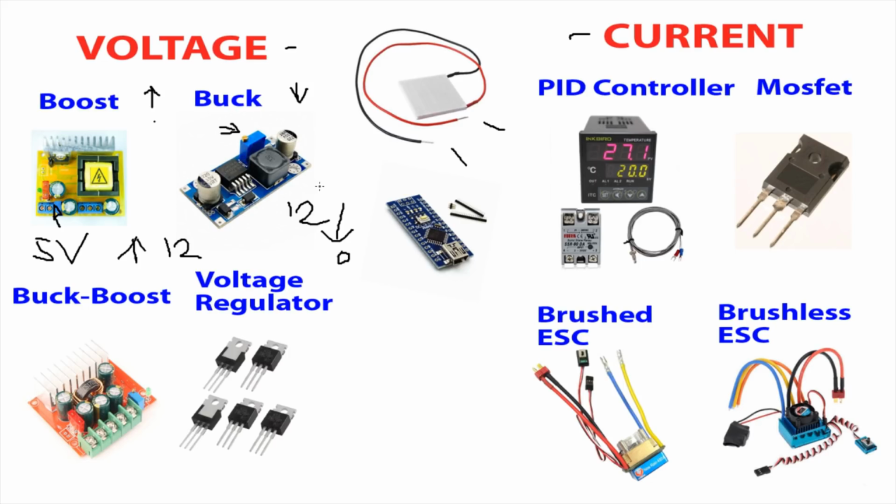But these are pretty jolly useful. You'll be probably powering it from a car or from a PC power supply. You want to control your 12 volt-ish TEC. You can then just turn the trim pot to adjust your output voltage, which will relate to a temperature. So these are highly practical, but be aware that you may not be able to actually stop all of the power going to the TEC unless it can go to 0. However, you may say if it goes to 0.8, the amount of power it's going to be drawing is so small that it's not a big deal, and you'll always want more than 0.